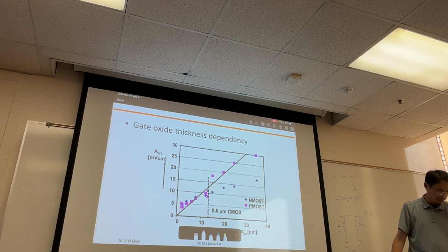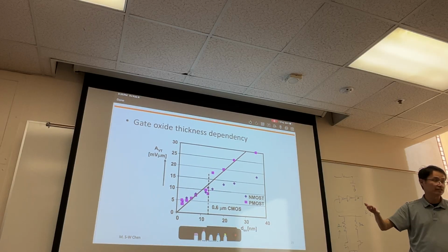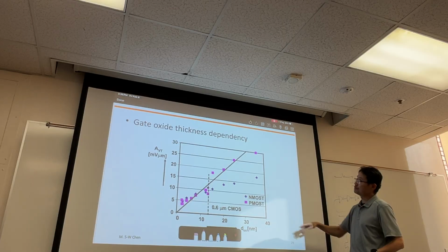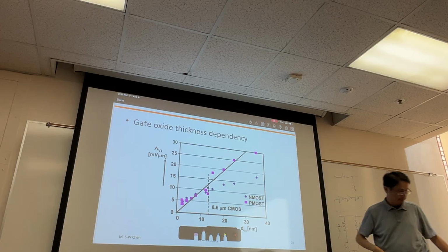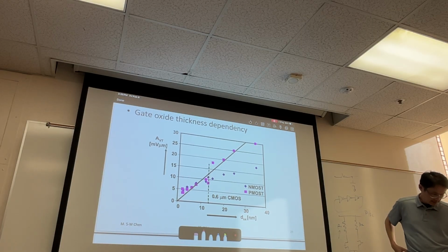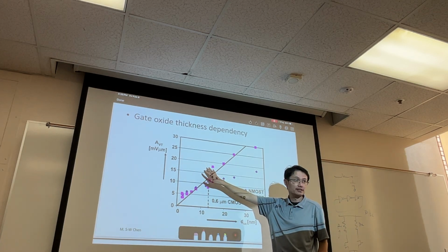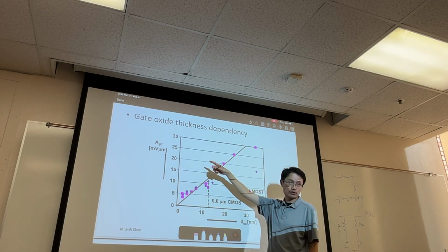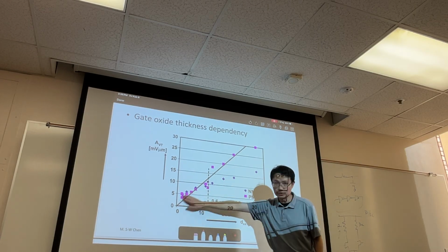However, even though we cannot control those process parameters, we can still understand, across different technology nodes, how this matching factor would change, right? In general, it's affected by the gate oxide thickness. If the gate oxide thickness reduces, you see this A factor reduced. Is that good or not good? Do we want the A_VT factor to be large or small? Small. It does go down. That's good.